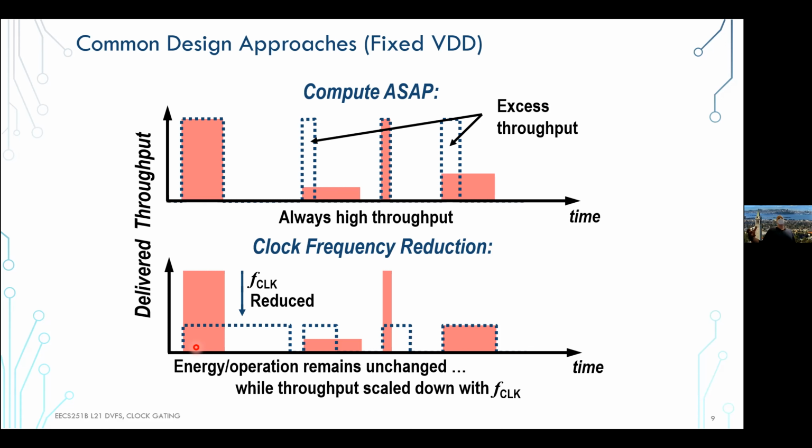For example, you are heating up your chip too much, right? So you want to quickly back off on power, right? This is still reasonable. You keep the supply, you basically scale the clock down. That just gives you a little bit more time, drops the power, and then you can correspondingly drop the voltage if you need to. But it is a measure that you can still use. It's not going to save you energy in the long run.